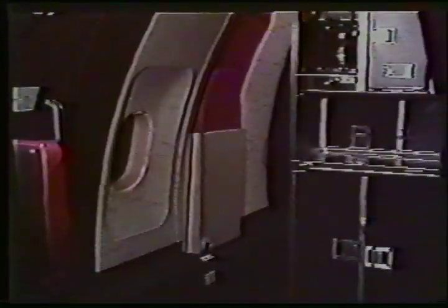The last 2 jump seats are the L4B and R4B. These are additional jump seats that stow away into the bulkhead. To remove them, simply pull the lever at the bottom and swing the seat out. Lower the bottom onto the locking pin and push down. To release it, push the button on the side, lifting the bottom off of the pin. Swing the seat in until it latches into place.